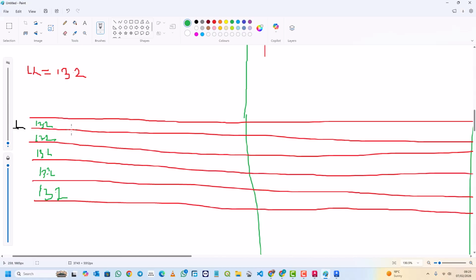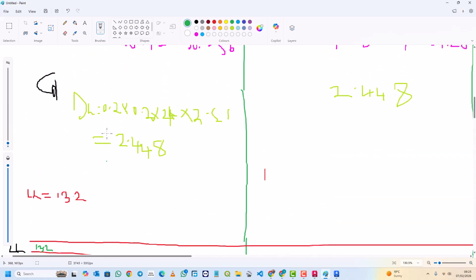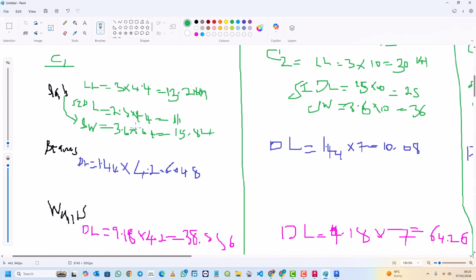The next thing is to get all the dead loads per floor. So it's also very simple. We will just add this 11. So please, you can take your calculator. For me, I'm taking 11. I'll just type 11 plus another dead load, this 15.84.